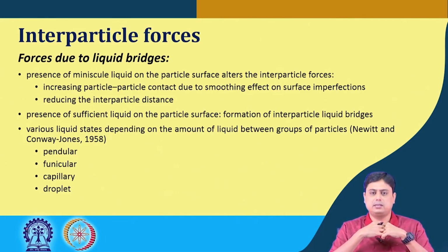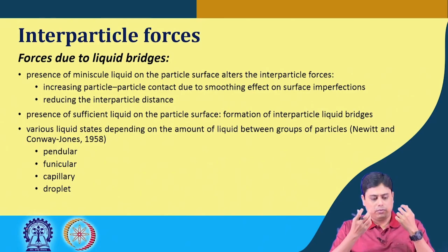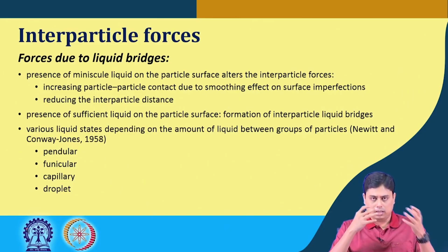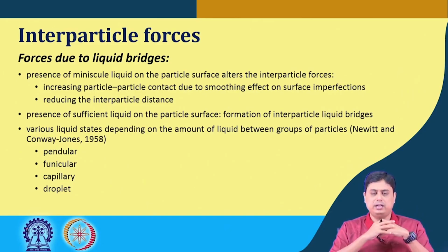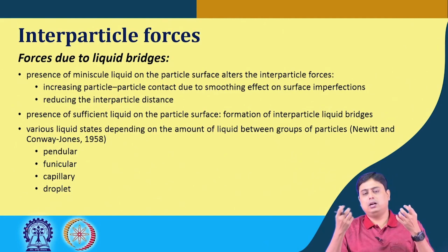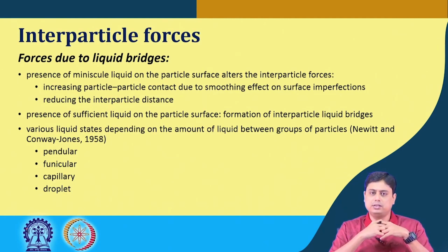interparticle distance. But if we have a sufficient amount of liquid on the particle surface, then the magnitude of the earlier discussed forces is not taken into further consideration. It becomes insignificant. Then what happens? It forms the liquid bridges.